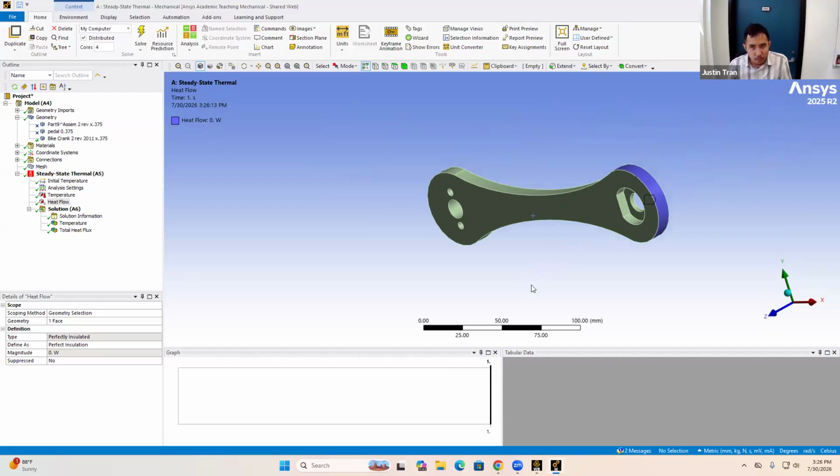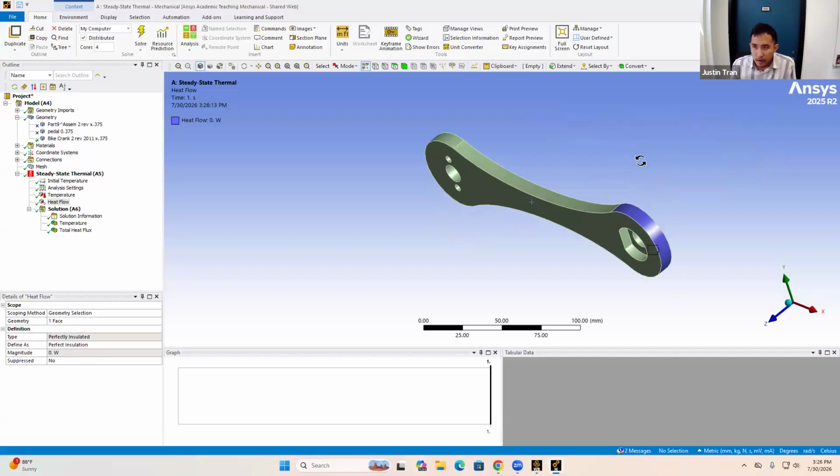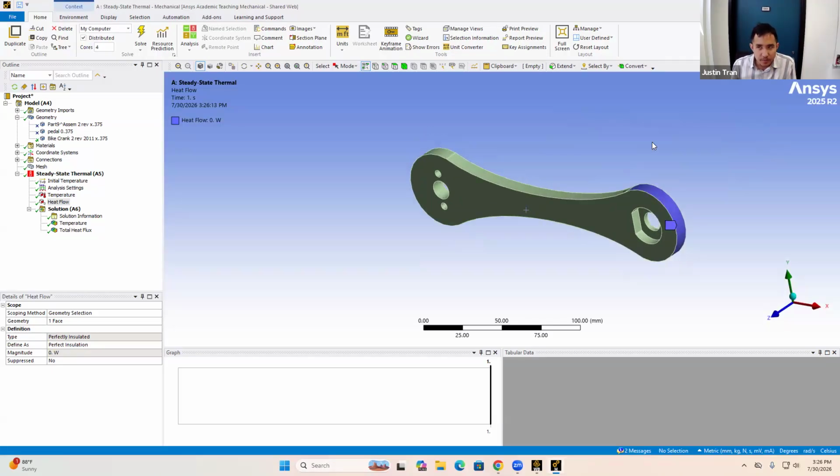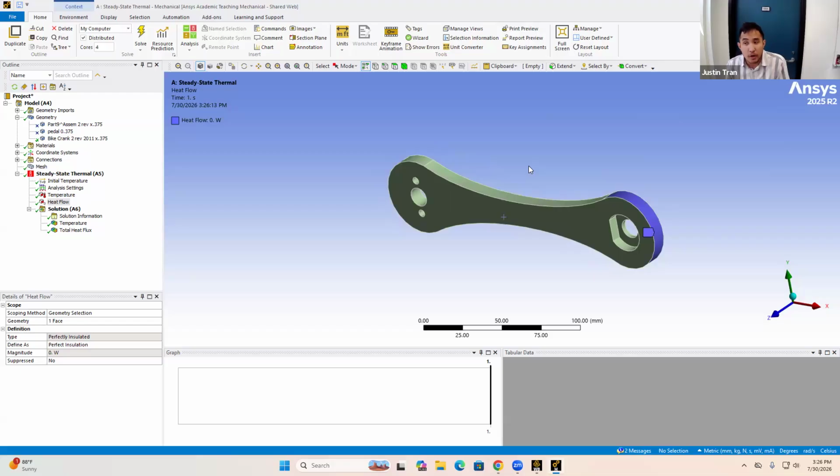Now, if you remember from our discussion of boundary conditions, even if we don't specify it, every exterior surface has to have some boundary condition assigned to it just because it's on a boundary. Whenever we don't assign a boundary condition to a surface, ANSYS is going to assign a default boundary condition. For a structural simulation, the default was a stress-free boundary condition, so essentially there's no load applied to it. That intuitively makes sense, and in fact, we've never actually thought twice about it.